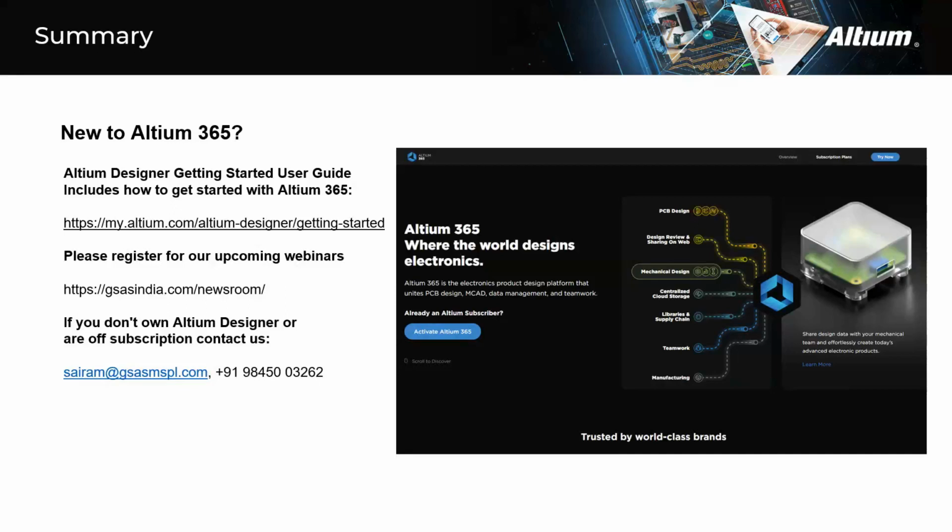And to overcome the challenges in the file-based libraries and the database libraries, we have shown you the Altium 365 capabilities of migrating your libraries and creating your component categories and templates where you can maintain your parameters as per company standard, and where you can appoint one person as a librarian so that he can manage all of that. And also, we showcased how we can set the roles and responsibilities, and how we can import your existing file-based libraries into Altium 365, and how we can categorize them based on their component type.